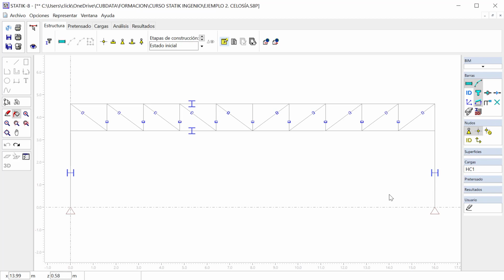Furthermore, the layers have a very obvious behavior that does not need to be explained, but if we want to annotate a structure, that annotation will go to a special layer, which is the user layer. As you can see, down here is the user layer, and it is special because it is the only one that you have to activate. You have to click the right button and say that you want to activate it. Notice that, as soon as we do this, on the left, a series of tools that were not activated before will activate. Among them, the dimensioning tool, which is the one we are going to use. You click and we see that they all appear.